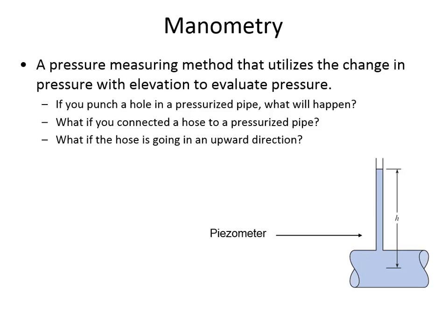A typical value in a water network might be 500 kilonewtons per meter squared. So the water level is going to keep rising until it comes into an equilibrium, until the pressure of the water from this tube is equal to the pressure of water inside of the pipe.